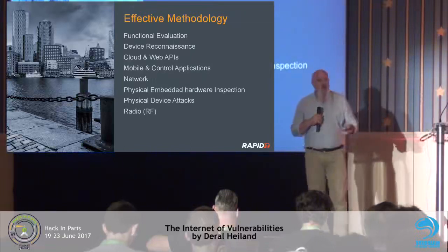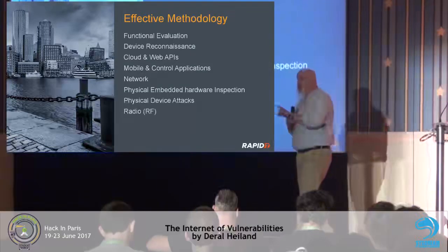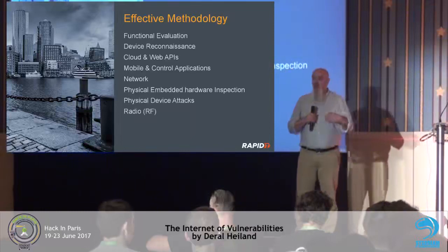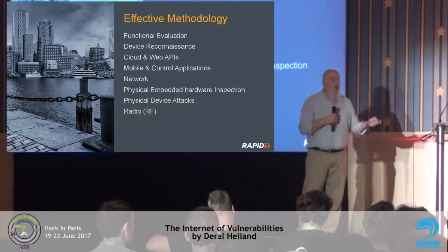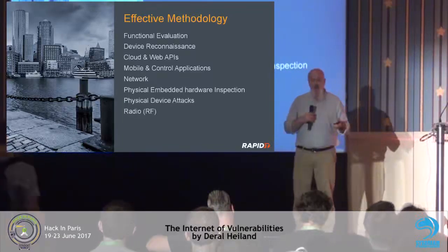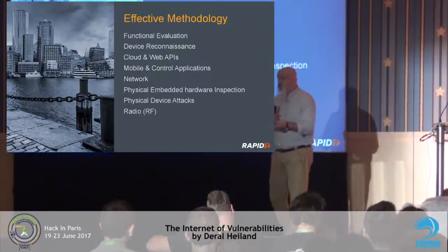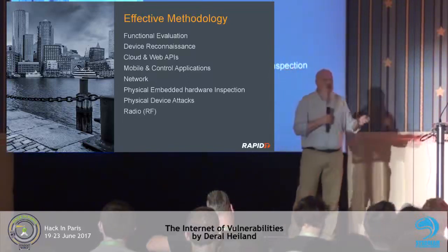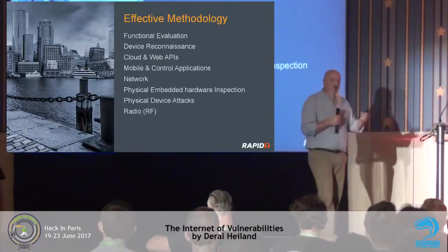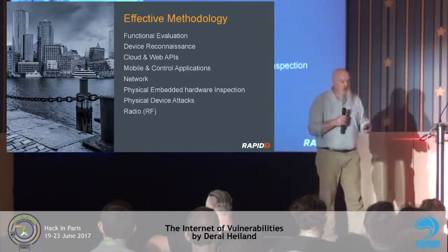That recon would also include looking at FCC information. You can pull the FCC ID off, specifically on stuff in the US and manufactured for the US. With that information, you can go to the FCC side and you can get interesting information. You can get a complete breakdown, images of the internals of these devices. You can get RF testing results, so you get a lot of information about the RF. On a few rare occasions, you can come across some schematics. But generally, that's what we do. We look at all the information that we can farm on that device.